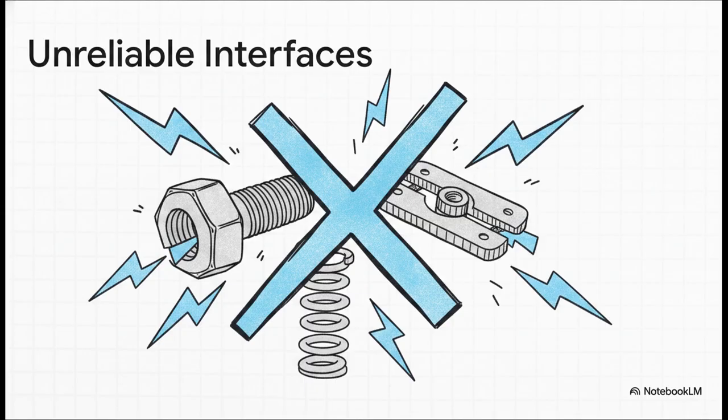Look, a standard multimeter might beep and tell you that you've got DC continuity, but DC is completely irrelevant here. Things like grease buildup, a thin layer of paint, or free body motion, think movable parts on a gun system or an industrial robotic arm, will easily degrade that contact. And when that happens, your RF impedance skyrockets and your shield is completely broken.